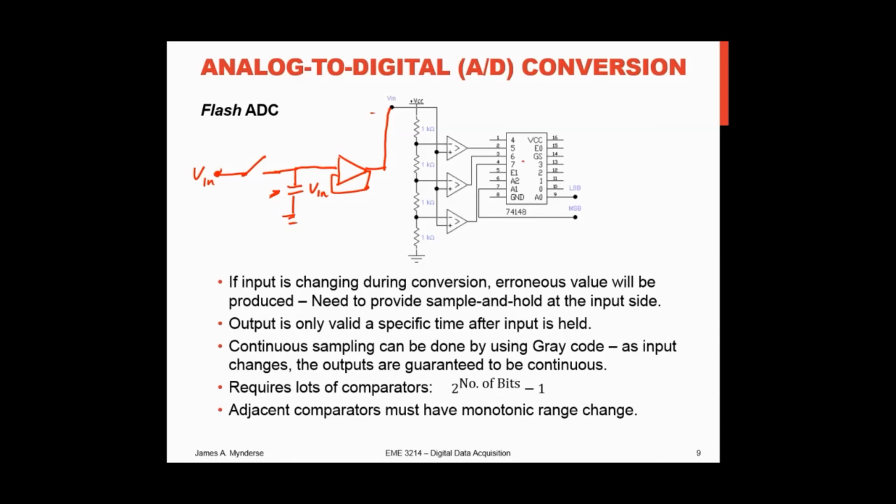So that's typical for almost any A to D converter. You really want to use this sample and hold. It solves a lot of problems for you. Many converters have that built in, like the Arduino or the Atmel chips that Arduino uses have that built right into it, so it just happens for you.